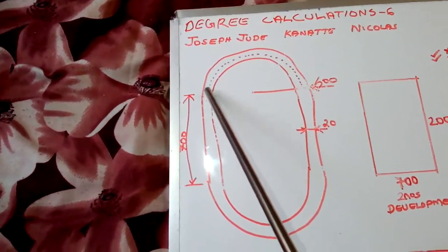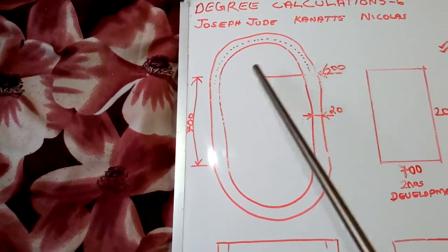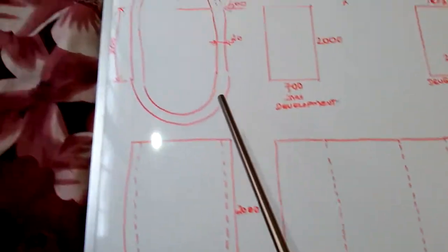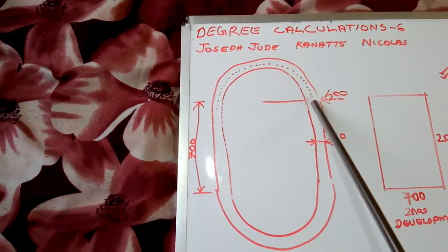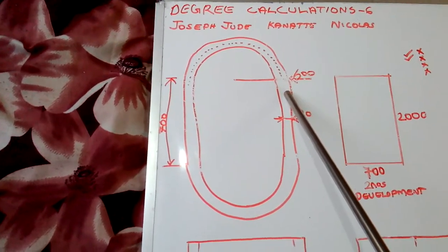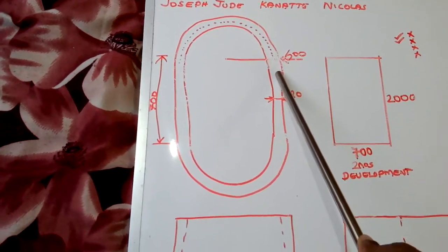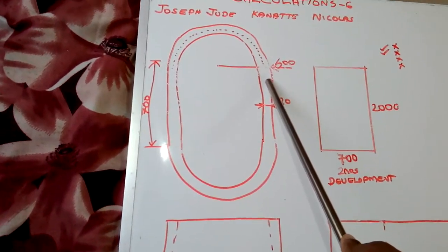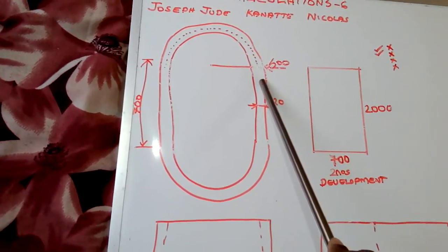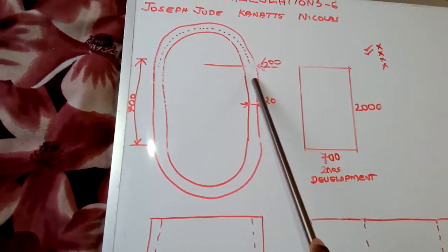Take 100 mm extra with this rolling. Actually, we need 1853.5 only. From this 1853.5, just add approximately 100 mm, according to your rolling machine. You add the proper measurement. If it is more than 100, you will have to add 200. If there is no need to add 100, some machines with 50 mm maybe do not get a proper rolling, so you have to add 50 mm only.